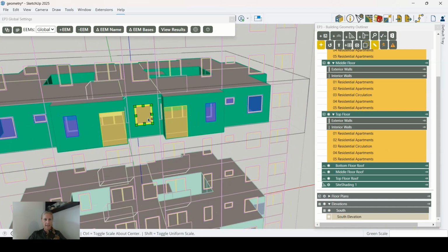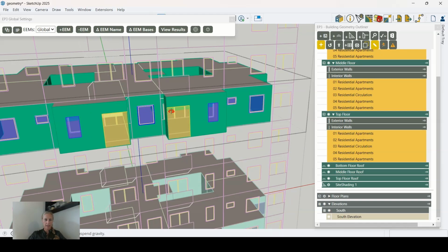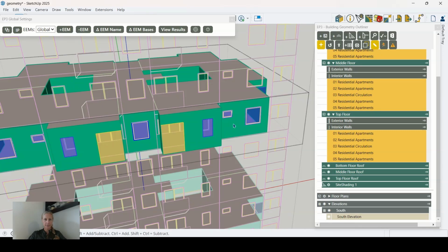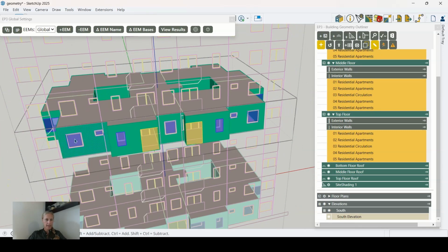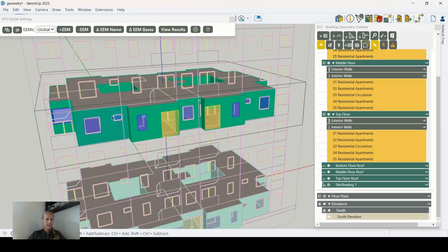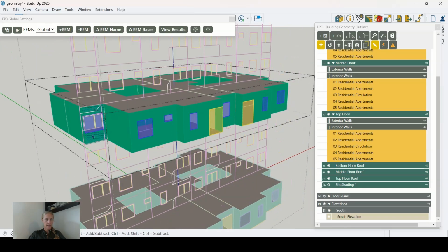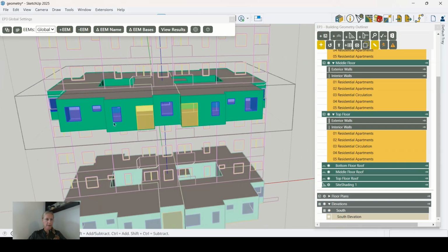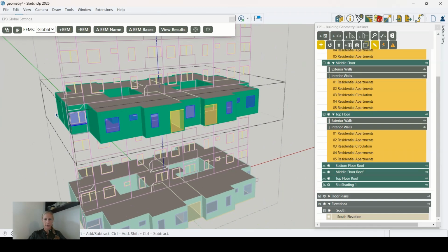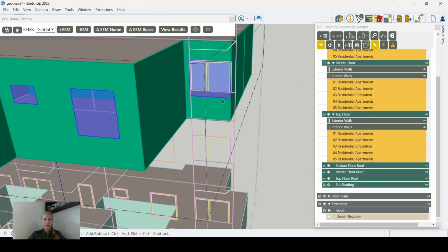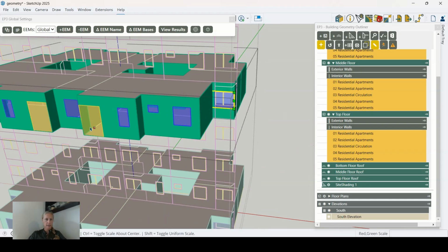So we'll change the size, and then I can get a different construction type. So it's paint bucket, and I'm holding down Alt to select a different construction, and then I just paint it. Okay, these windows here look okay, and I think this situation is going to be the same where we have full height doors. So again, select both, stretch tool.